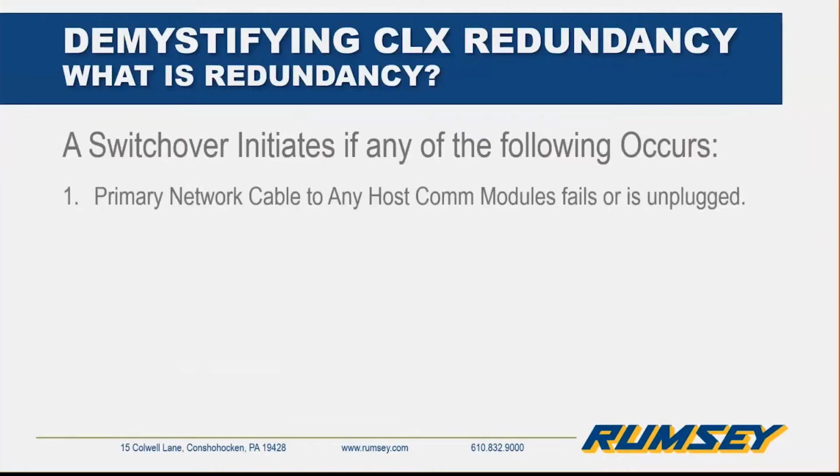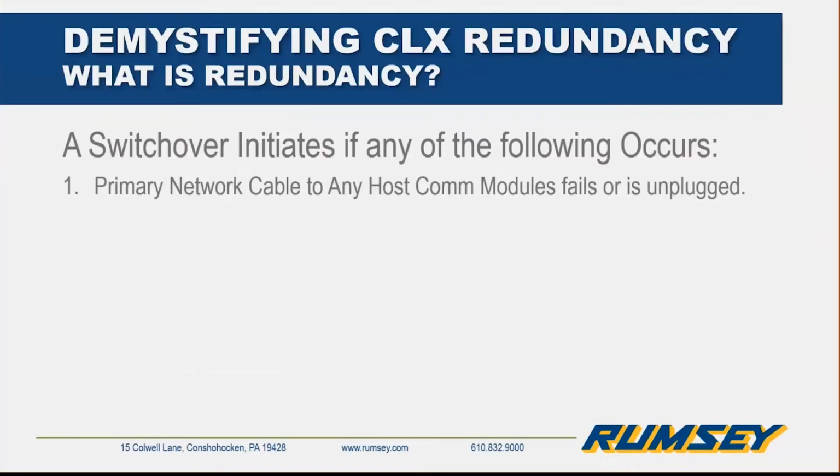All right, switchover. What causes it to occur? If the primary network is unplugged or becomes defective, whatever the case is, because it's monitoring everything, that host, it will flip. Any COM module failure. Most commonly when I see this happen, somebody uses a non-Allen-Bradley switch, some sort of spike goes into the Ethernet module, zings it out. If that becomes unhealthy, again, it causes a switchover to the secondary.